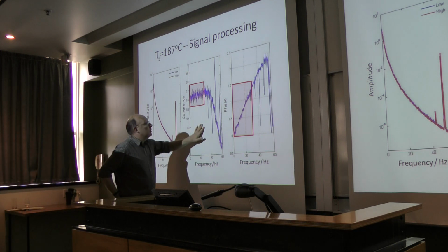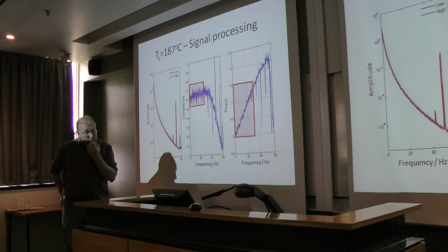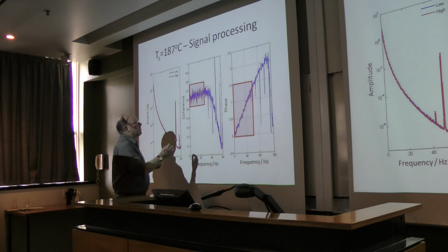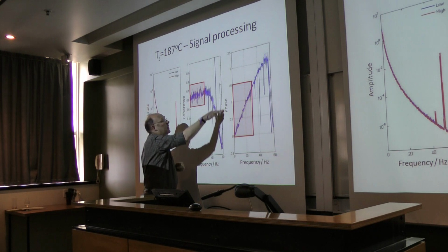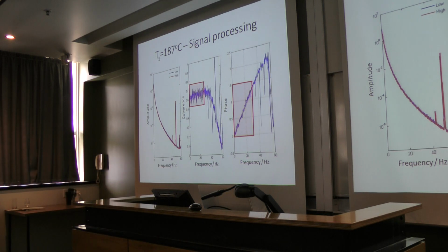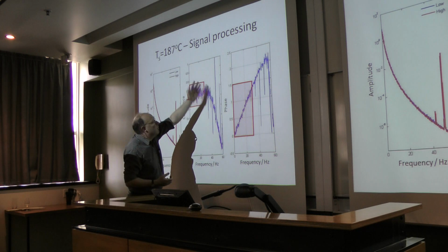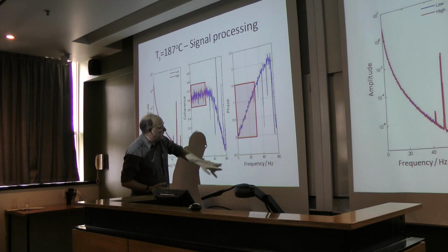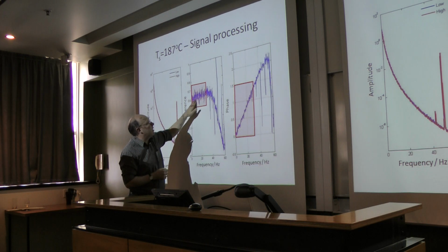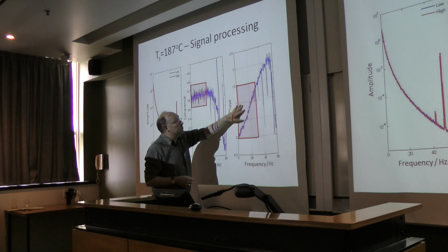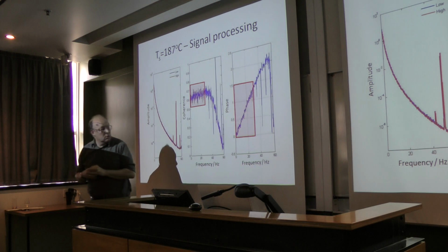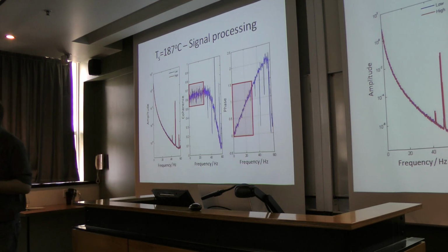But now if we move on, we've got two graphs here. They're really convolutions of the two time series, and the two things we're looking at are coherence and phase. With coherence, what we're looking for is a non-zero coherence that is not all over the place. Here it's going crazy at the higher frequencies. So we're interested in this part of the data. And the phase, which is what we're going to get the velocity out of, we're looking at a nice linear phase-frequency relationship, which is what we need.